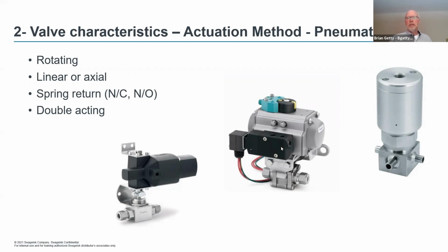Double acting, with this one here, you can see it requires air to make the valve open, and it requires more air to make the valve close. So you need air for both directions. And on a linear valve, it's the exact same thing: it takes air to open and air to close.